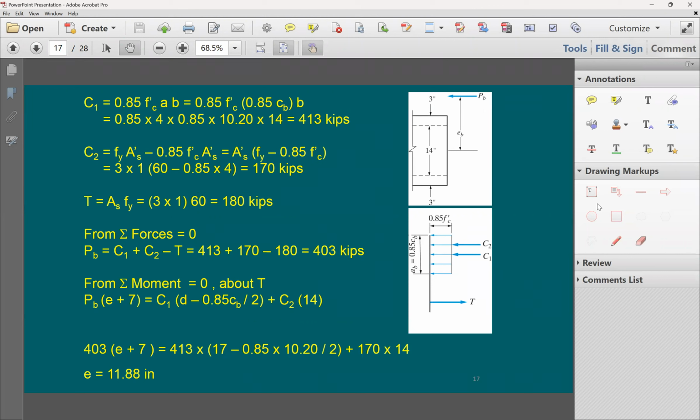If you'd like to find x to determine the maximum moment, x is going to be here. It's going to be this. So you have the total footing length, subtract the column width, divide by 2. You don't need an equation, right?